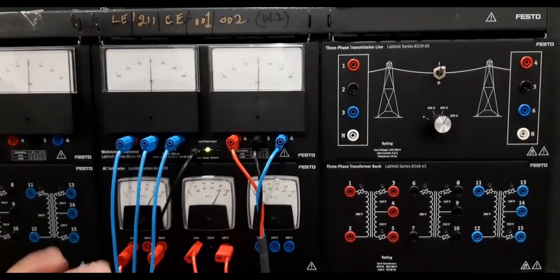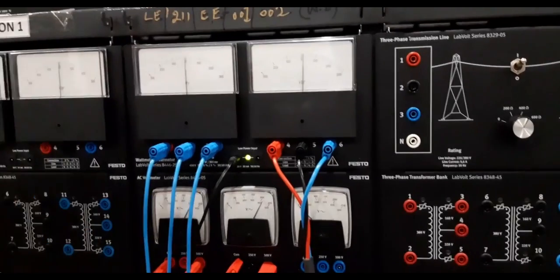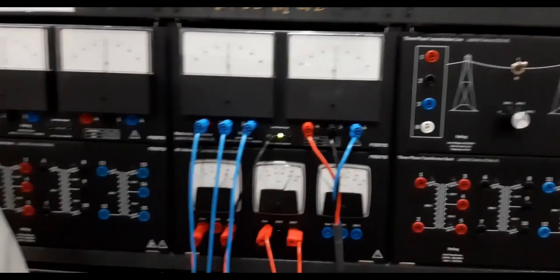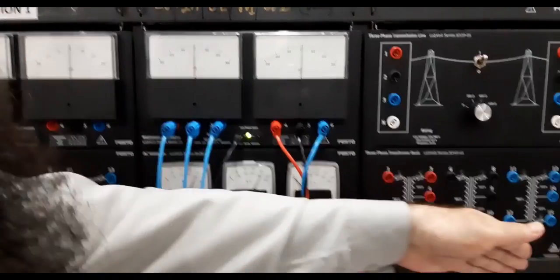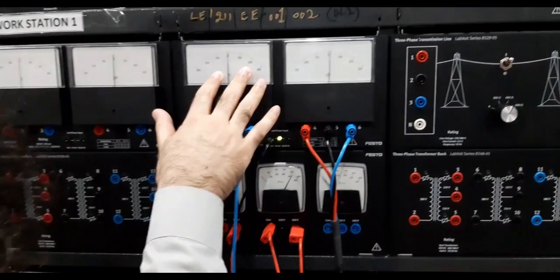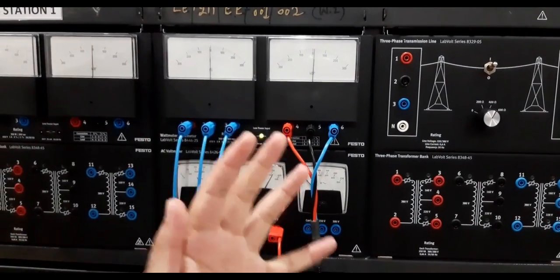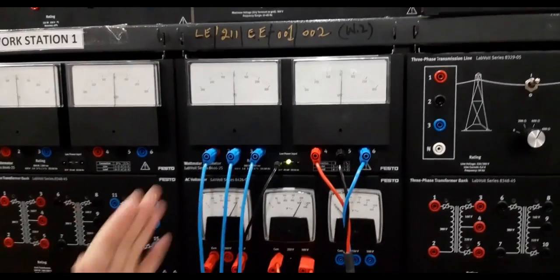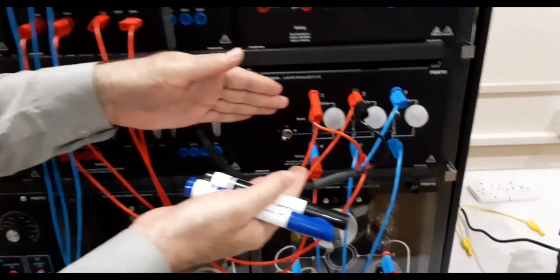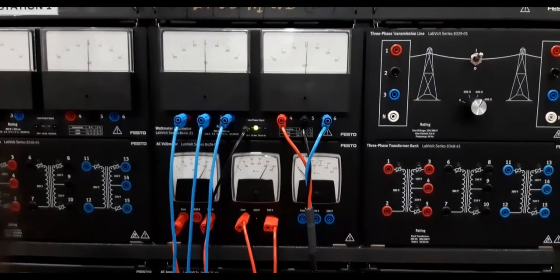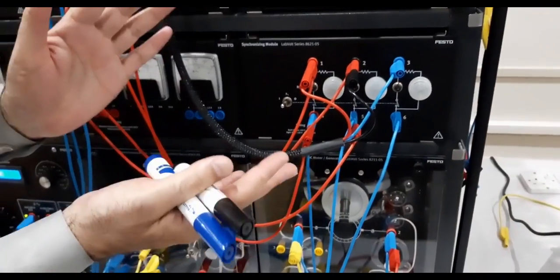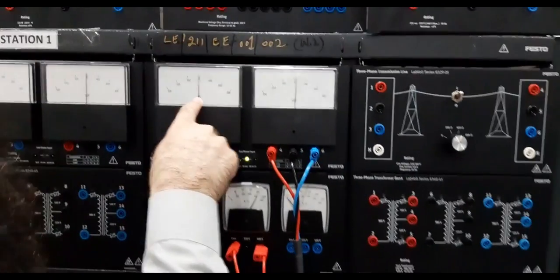Also, because we talked about that the system voltage and that of the synchronous generator are the same when even the phase angle is the same. And since the two voltages are the same, it means there is no phase angle difference. So that's why, because the active power is sensitive to the angle between the induced EMF and the terminal voltage, and because now the two voltages are the same, and these are phasor quantities, and phasor quantities will only be the same when the magnitude as well as the angle is the same. Since these two are the same, there is no angle between the two quantities. So that's why active power is also 0.